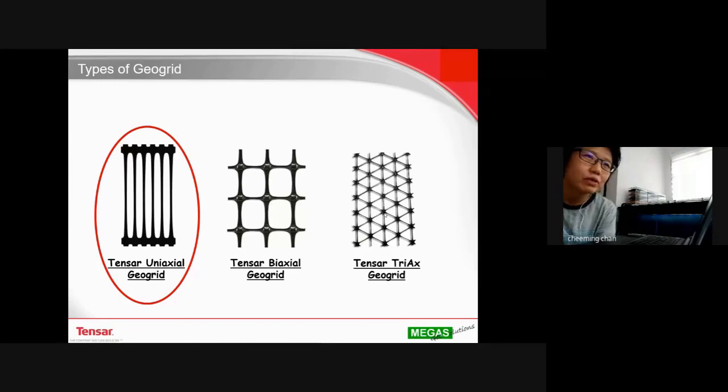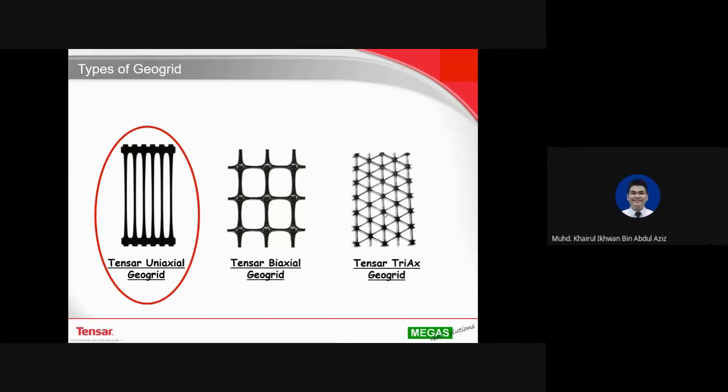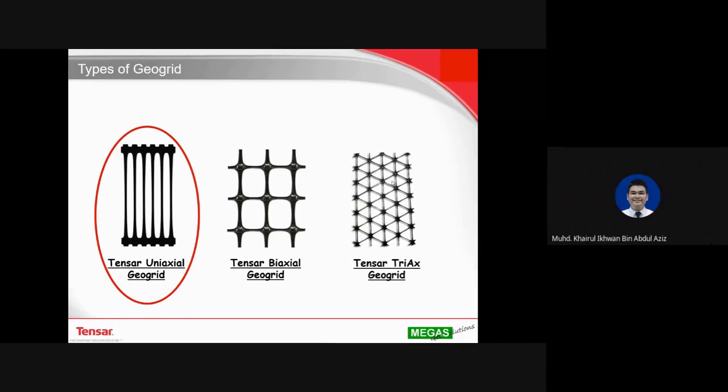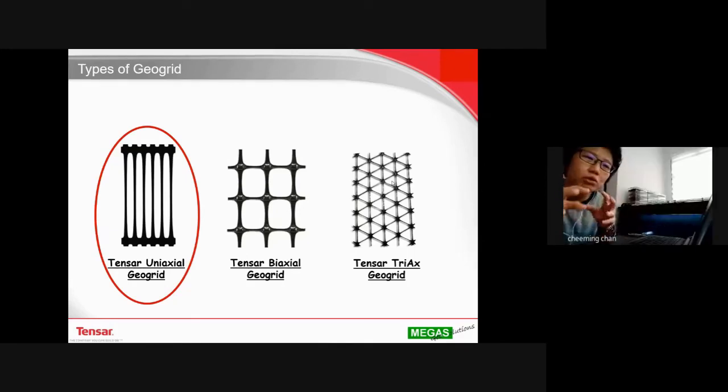Because the focus of Dr. Lok's talk was actually on using the triax geogrid for road pavement improvement. Remember that? It's very much about interlocking and how this triangular shape structure will help to hold your granular materials in place, like what Mr. Chan has just said. To build a flexible pavement, the materials used are simply put stones. If they're stones, that means they're granular, berbutir lah, sebiji-sebijinya tu, and they're angular. So on their own, they are already interlocking themselves when you compress. But when you have this geogrid in there, it will give extra stiffness and extra strength.